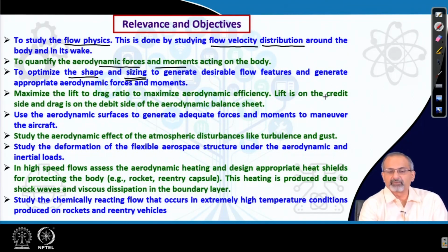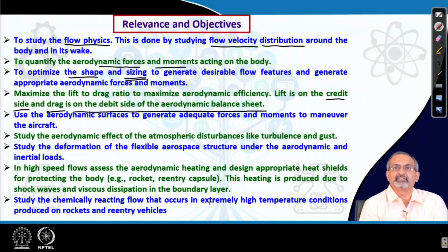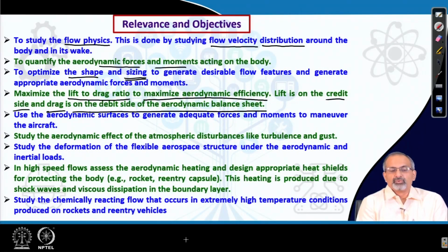Lift is a kind of a benefit while drag is a penalty, and therefore, you may say that lift is on the credit side and drag is on the debit side of the aerodynamic balance sheet. You may like to maximize the lift to drag ratio to maximize the aerodynamic efficiency of the configuration. You use the aerodynamic surfaces to generate adequate forces and moments to maneuver the aircraft. So, you may need to know whether the surfaces are correctly scaled, correctly sized.